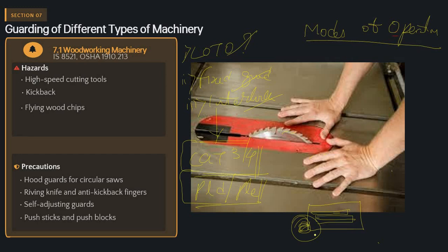People normally think that whenever they lift the door, the machine gets stopped. But sometimes the interlock malfunctions or is bypassed. They think that when they lift this, the machine stops and they can remove the jam, but it's not stopping. People place their hands between two dies, and amputations are happening. So that is one.